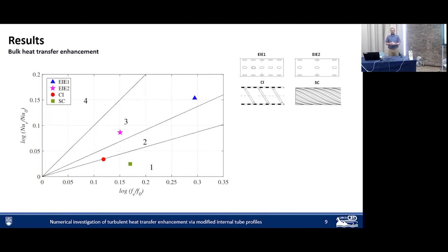We looked at turbulence kinetic energy transport equations, all of these things. What we found was the most explanatory was this correlation term between the radial velocity fluctuations and the mean temperature gradient in the radial direction. Nothing else was quite as clear in explaining the interaction between the heat transfer and the turbulence. Thank you.